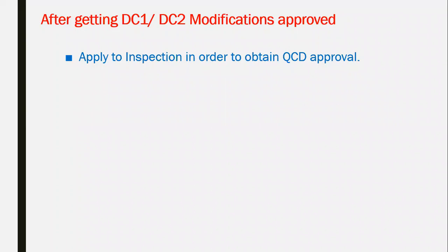And during the inspection, you have to prepare a complete set of the drawings for the layout plans and all the systems, and we will talk about it. Either for the life safety, it's one task. But if we are talking about firefighting and smoke management, all the layout plans, the schematic diagrams, the riser, copy of all the calculations and the sizing calculations, copy of all the material submittals with the certificates, and samples for all the devices, whatever could be provided within the sample room.